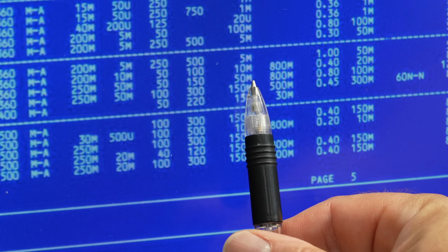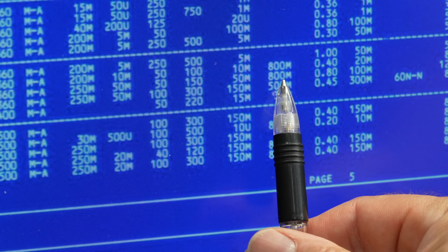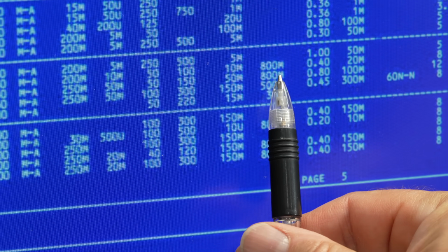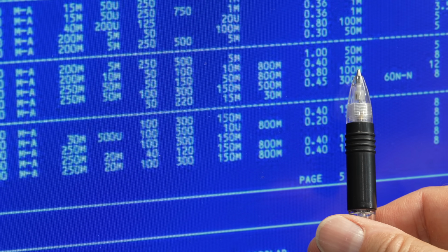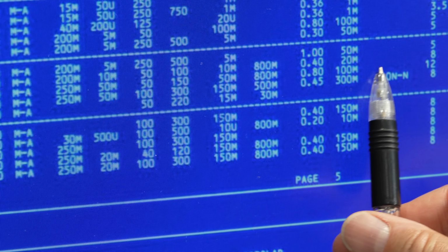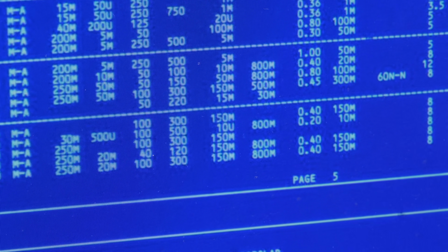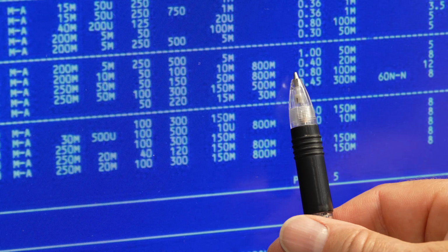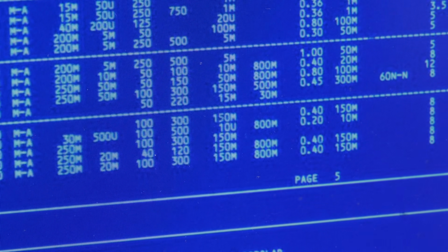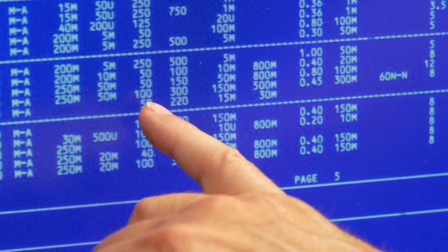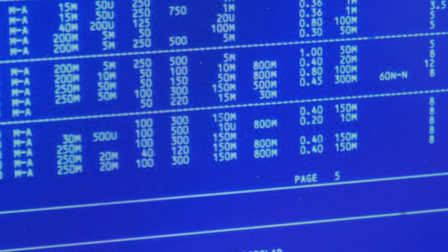So it's a transistor made to work in the few tens of milliamps. 800 milliamps max. VSAT not that great, 0.8 at 100 milliamps, so it's meant to be driven relatively hard. There's no equivalent to this, but I would bet you a 2N2222 would do perfect here. It's about the same frequency, and it's made to drive quite a bit of current too.